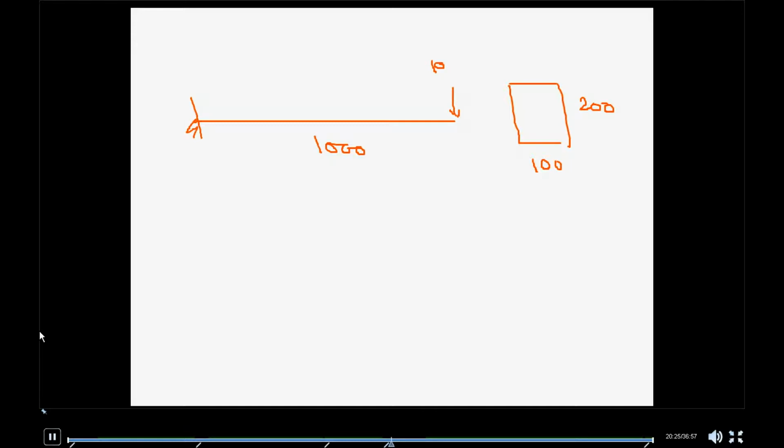Okay, now we will try to solve this problem and try to understand these element types and element concepts, different sets of the elements in 3D. Before I solve any problem, as I said, you should remember these 4 stages. Now you might wonder why I am saying 4 stages. Don't forget the pre-planning stage. So the 0th stage is pre-planning, the first stage is pre-processing, then second is solution, and third is post-processing.